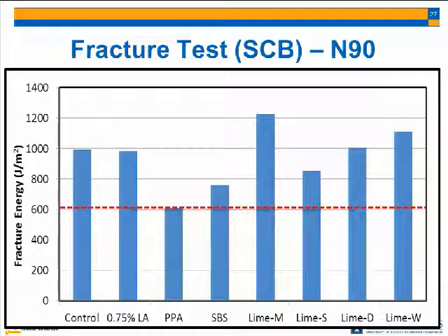But when it's inside the aggregate, something maybe Ibrahim forgot to mention is that some of this moisture is in the aggregate when you coat it with asphalt, because when you heat the aggregate for just a few seconds, like 30 seconds, you're not getting all the moisture out. So some of it even gets inside the aggregate, and when you coat it with asphalt and cool down, it starts coming out. Hopefully, when we heat the aggregates, we assume that we get rid of this moisture, but still we will have some at the end. Yes.